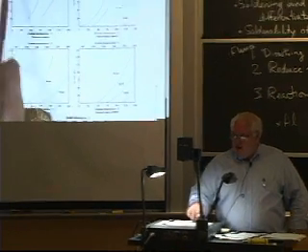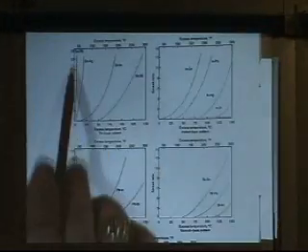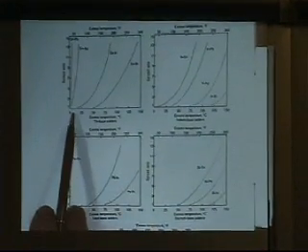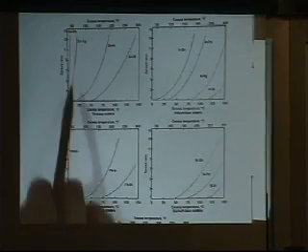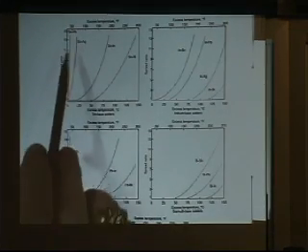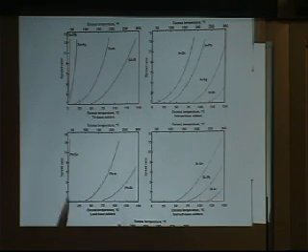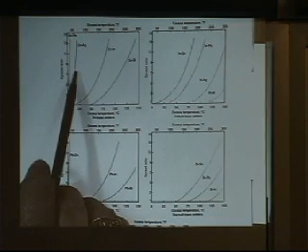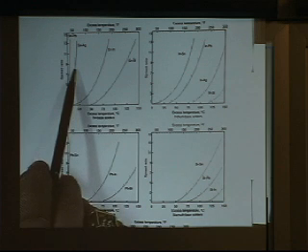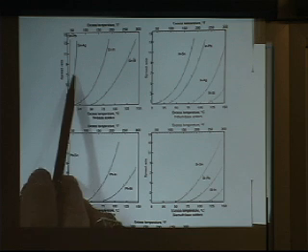But in any case, we're trying to replace lead tin, and if you look at the tin alloys, look how easy it is, with almost no increase in temperature, an excess temperature of 25 degrees Fahrenheit, you can get lead tin flowing and spreading out wonderfully. But if you go to tin silver alloys, which are some of the things that people have been replacing it with, and certainly what people have used in the plumbing systems, they've started using tin silver alloys.